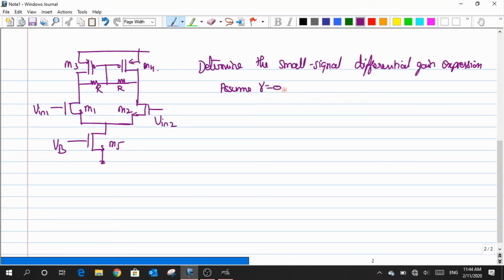For this given circuit, how would we analyze the circuit and get the differential gain out of the circuit? Yeah, so first of all, is the circuit symmetric? That is the very first phenomenon that we need to consider here. Can we draw a line of symmetry for the circuit? Yes. Okay, so when I try to draw the line of symmetry, it exactly comes here, right? So I have one part which is an exact replica of the other one.